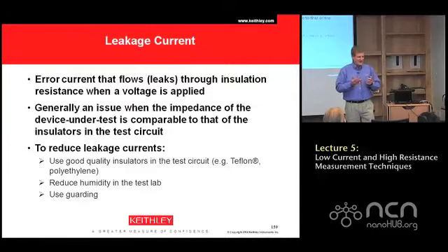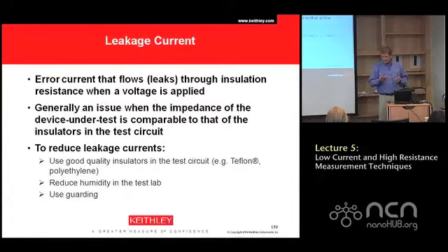You come in at 9 o'clock, or if you're like some students, you come in at 10 o'clock. And you know, it seems like it should be good, right? But everything has been soaking in humidity all night. So one of the things you definitely want to manage in your laboratory is maintaining the humidity and temperature around the clock. Okay.